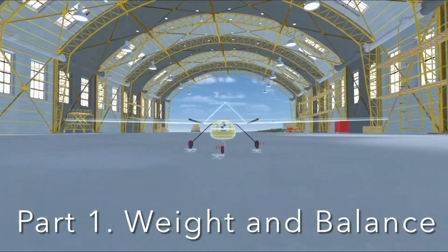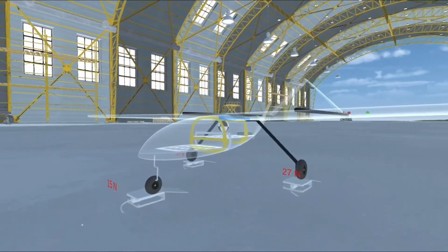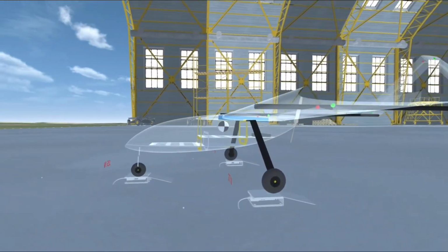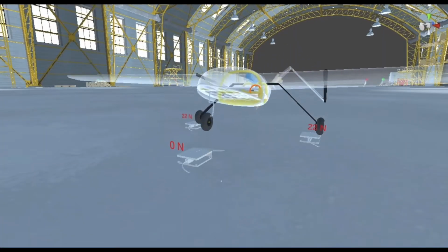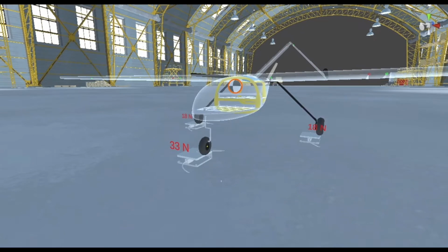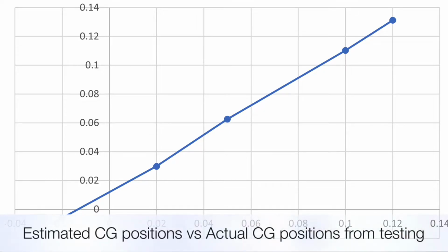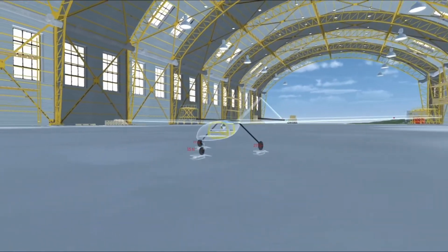One of the preliminary tests that must be carried out is a weight and balance test. This first verifies the mass and CG positions from measurements of the wheel reaction forces by measuring the moment arm of the port, starboard and nose gear. Then, using the respective loads to calculate the CG position. This will help you to determine the handling properties based on ground handling and the management of load within the aircraft, to ensure that the aircraft performs as expected.